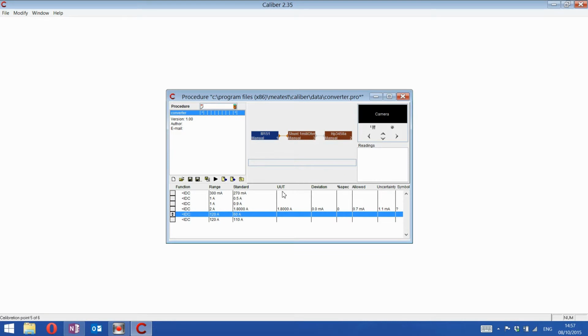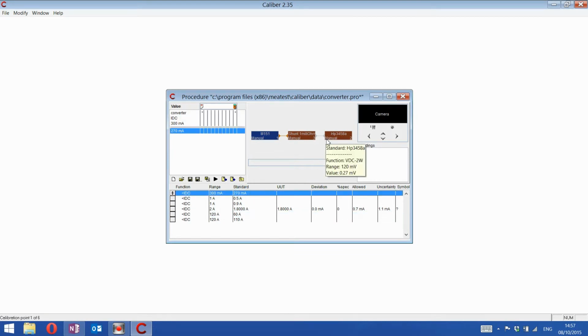The lowest ranges of M151 are actually far too low to use 1 mΩ shunt, so it's better to connect the M151 directly to meter's current terminals. This procedure is very short, so it's okay to rewire the instruments manually, but using manual instruments in longer procedures means that you run the procedure, wait for 10 minutes till it gets to some point, rewire the instruments, run the rest and wait another 10 minutes, rewire again. Inconvenient. You can use a hardware switch instead.